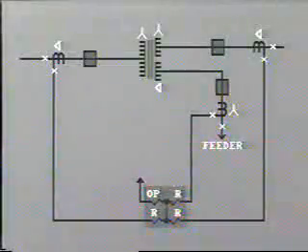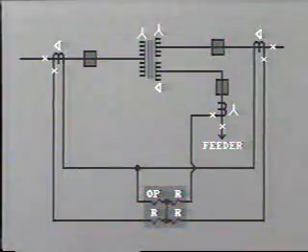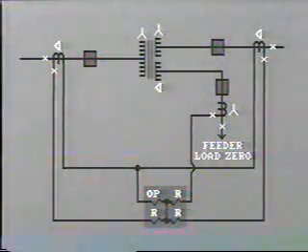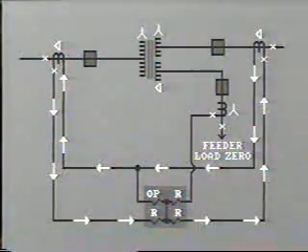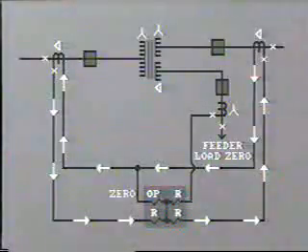In this single line diagram, you can recognize the connections to one phase of the differential relay. However, in following through the operation, it helps if we connect the other end of each CT, first, for the two outer windings. If we consider the load on the third winding to be 0, we can see that there is balance here. The same secondary current passes around this circuit with no flow through the operating coil.